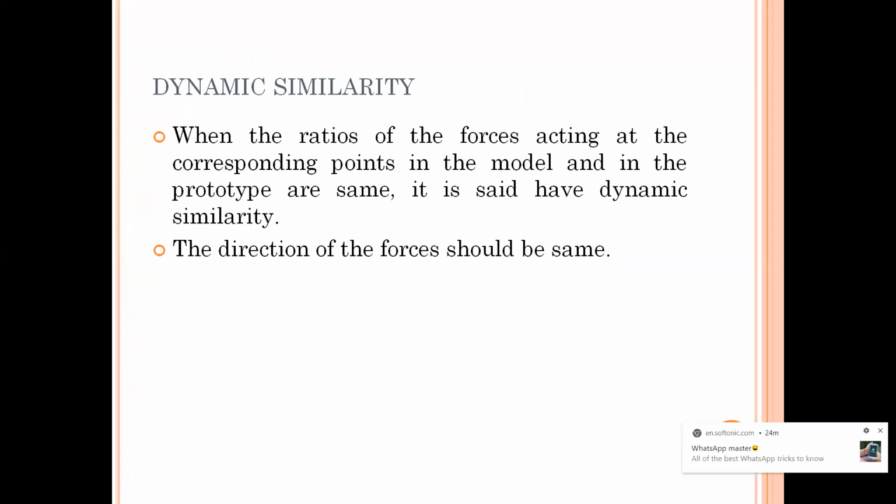Now next, coming to your dynamic similarity. So here we are dealing with forces. When the ratio of the forces acting at the corresponding point, so here also your corresponding point is important. When I'm considering forces, there are different types of forces. So we are considering the force at a particular point and we are finding the ratio in the model and the prototype. Then it is said to have dynamic similarity.